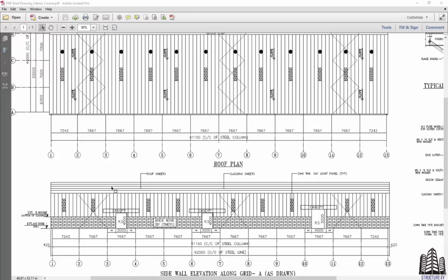So basically what I am trying to say is that suppose a horizontal force travels like this. PB sections itself have very little horizontal load taking capacity. So this force will travel from this point to this point. So it will come in compression and this will come in tension. Similarly here and similarly here.